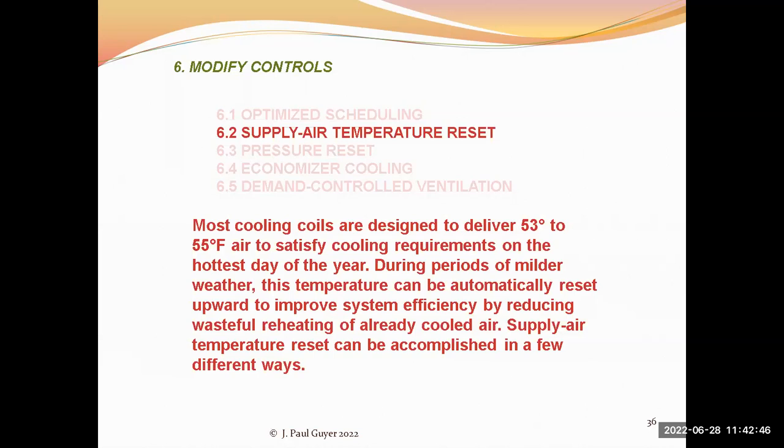So with an outdoor air temperature sensor, when it's cooler outside, this cooling coil discharge temperature can be adjusted upward to provide energy efficiency improvements. So supply air temperature reset can be accomplished in different ways.